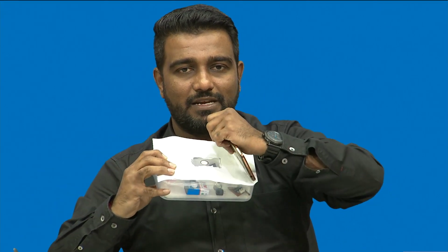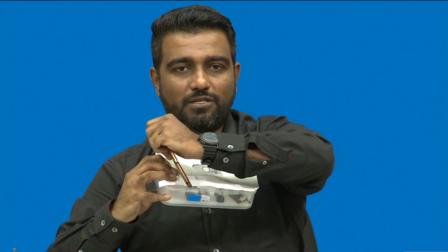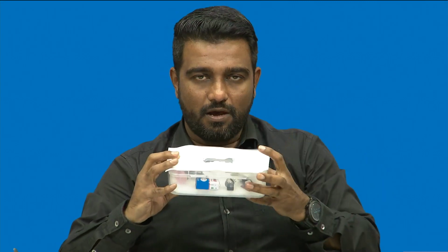If I have a material which is my sensing material and I use a squeegee, understand that there is a sensing material here. If I squeeze it like this on this particular substrate, the material will pass through this particular hole, and the remaining area will not be affected.